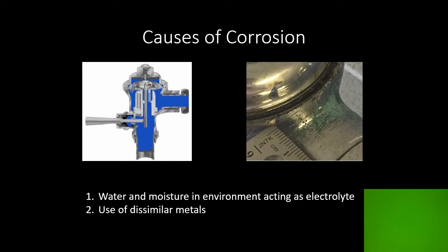Corrosion is a chemical reaction with components of its environment. In the case of our observed parts, there is constant exposure to wet, warm, salty, and oxygenated conditions, consistent with that of a male washroom. Our observed part was iron-based and chrome-plated to resist corrosion. The dissimilar metals used make our parts susceptible to galvanic corrosion, as iron and chromium have different electrode potentials, with water and moisture present in the environment acting as an electrolyte.